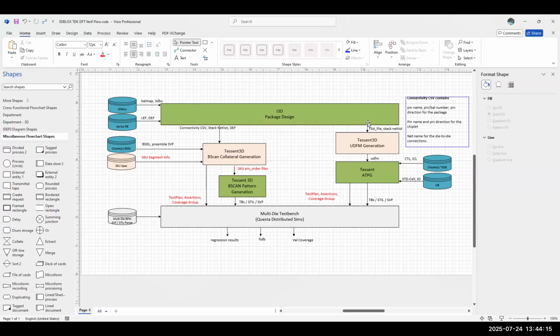It specifies the virtual RC delays between the IOs. It gives an abstraction level for the tool to say that there is a potential victim and aggressor scenario. This is similar to what you use with an SDF for the timing annotation. You use the netlist for the logical and then timing through the SDF, and the tool annotates both together and identifies the critical timing paths. So UDFM defines a virtual path between the IOs, which are neighboring IOs, and it models that.